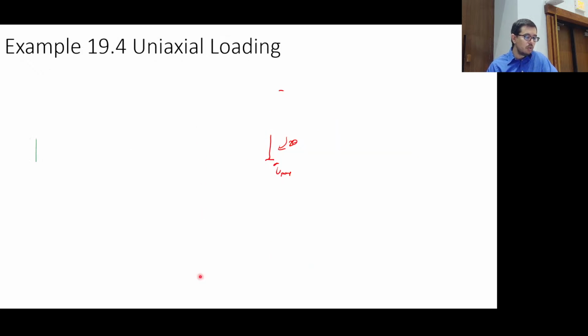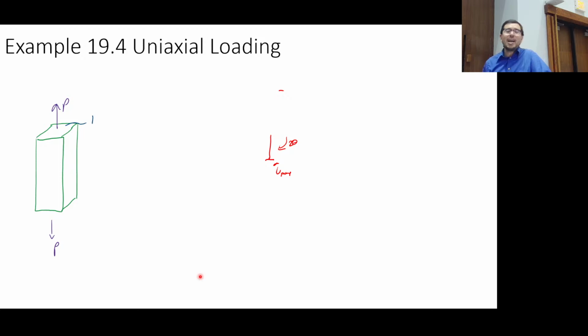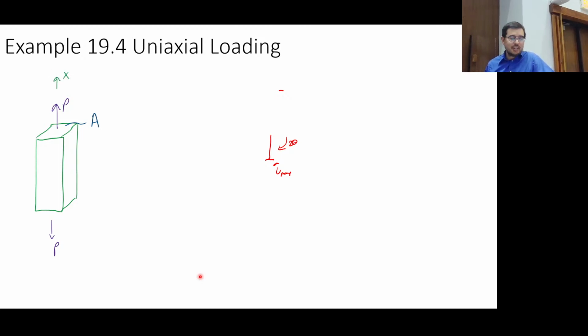Okay. So let's go now to uniaxial loading. You're like, what? We're going back to like session 2? Yes. All right. So what is the axial stress here? If we know the P, we know the A, it's just P over A. Now, this is uniaxial loading.